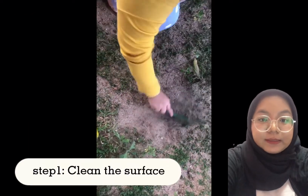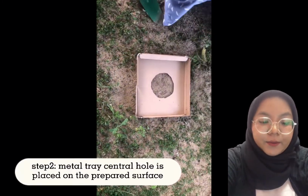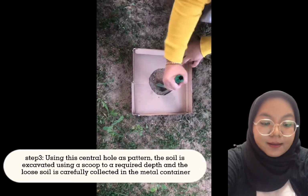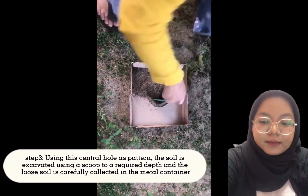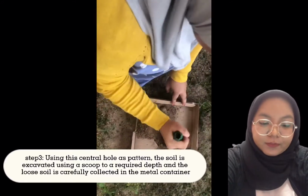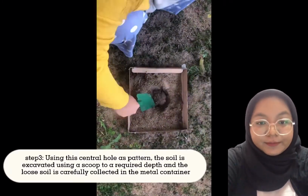For the sand replacement method, first we need to clean the surface at the site. Next, place the metal tray on the surface. Next, using the central hole as a pattern, the soil is excavated using a scoop to the required depth, and loose soil is collected in the metal tray.